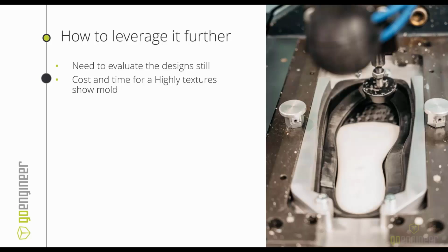Because when you're 3D printing molds, the printer doesn't care how complex the geometry is, right? That's something that was in CNC, it was directly correlated to price and time. Now with 3D printers, when you're printing something more complex, more details, the printer doesn't care. In fact, it actually ends up making the part cheaper if you're able to use, say, topology optimization or something, to cut down the weight and size of parts. You can print actually faster and cheaper, so it's kind of an inverse to how it used to work.